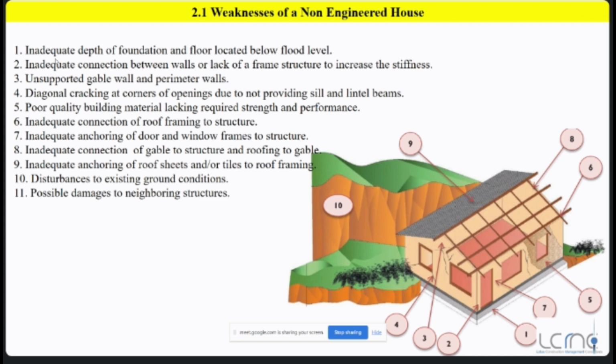What you have to do, definitely you need to provide a stiffener beam in the middle section of the wall. Otherwise the dead weight, the self weight of this wall, it can't bear itself. Definitely it will be a reason for the crack formation of that particular wall.